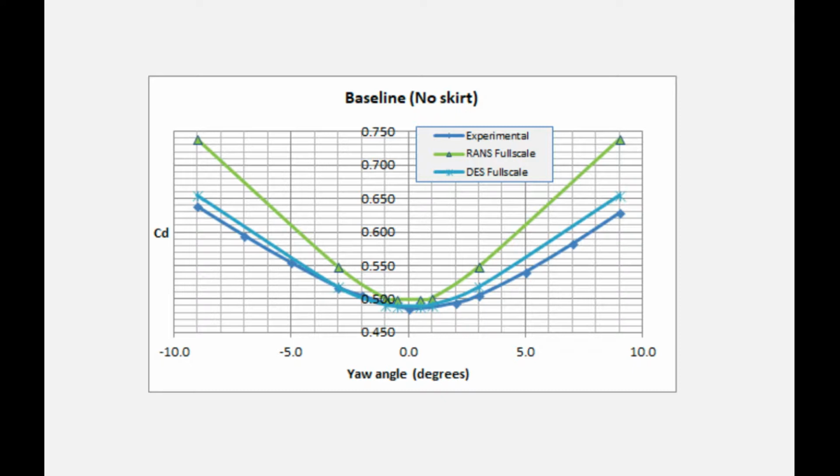And the other thing we recommend is that you perform several iteration points of the wind speed yaw when running the test of each design. What that means is I'll run a simulation at 0 degrees yaw, which is to say that the wind is impacting the vehicle directly.